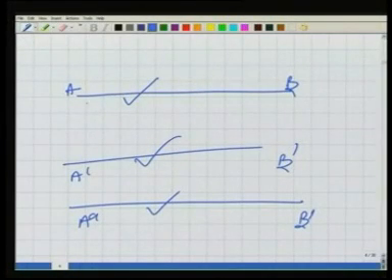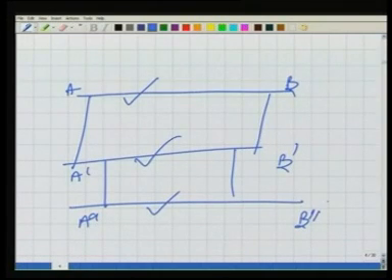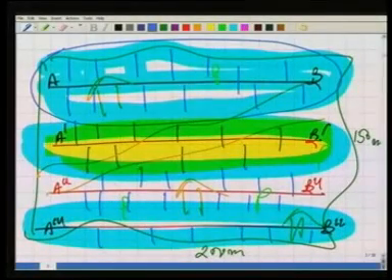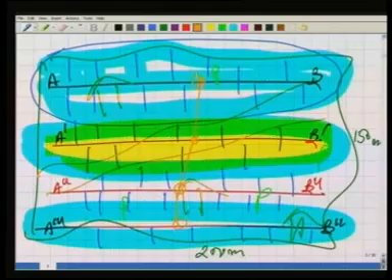There have to be some measurements which connect these together. If you cannot connect them, where to plot? So relatively they should be fixed on the ground. We can go for a thing like this, but we need to take some extra measurements which relate this chain line to this chain line and this chain line to this chain line, so that we can fix them relatively also, and this is how we can plot the area.